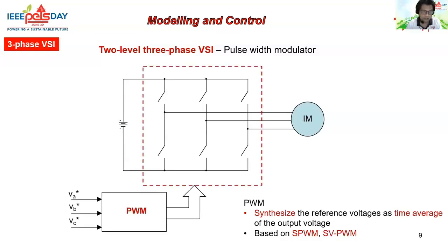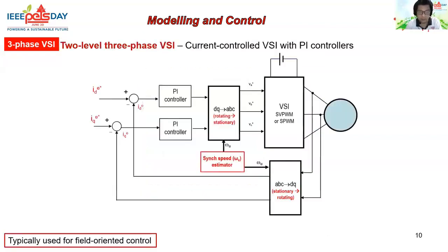The way we do it is that we are actually linearizing the output voltage of the converter over switching time, which means we are removing the nonlinear behavior of the inverter. The relationship between the reference signals and the outputs becomes linear, so we can control the inverter using a linear regulator, such as the PI controller shown here, which is used to control the current.